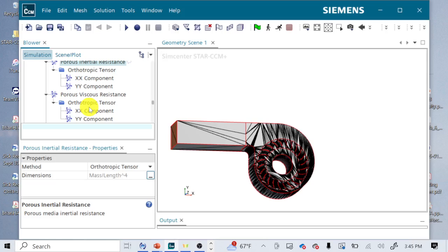Now, that theoretically looks pretty much the same no matter which way you go through it, right? It's not perfectly regular, it has irregularities, but whether you're going one direction through a sponge versus sideways relative to that, it's probably roughly the same resistance. In something like that, you wouldn't need different resistances in different directions. But what was the other case I mentioned? If you have like multiple fins stacked, then if the fins were face down. In general? Yeah. Fins. Well, okay, if you have a whole bunch of fins, it's going to be slightly difficult for air to move that way through them. It's going to be very difficult for air to move that way through them, right? Theoretically, air just straight up shouldn't be able to go that way at all, assuming these are solid, right?